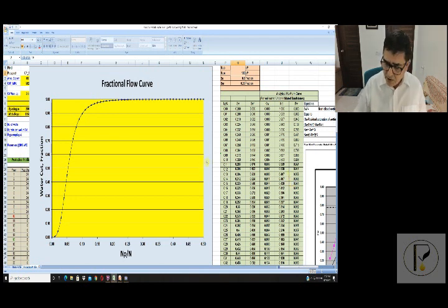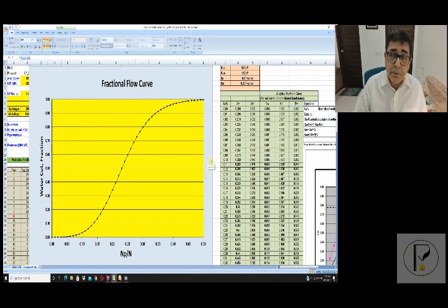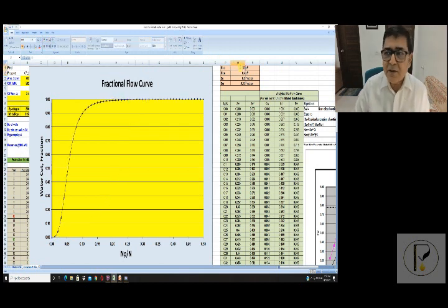So someone straight away, if the reservoir temperature is very favorable, very low, that means cold reservoirs, as well as salinity is very low, like fresh water, well, polymers, like in some countries in South America, have been very successful. Right from day one or day two, right at the end of primary, attempting polymer flood and getting a substantial amount of oil. Polymer is relatively easy to operate than steam, but both have their merits and demerits. Both have their advantages and disadvantages. But both yield incremental revenues.